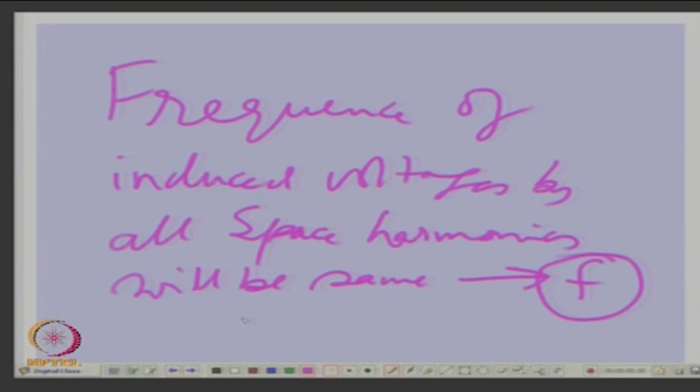But if you want to make things complicated, if the current going into the winding has time harmonics, the current is not sinusoidal. Nowadays with power electronics you make everything very messy anyway. So, current carried will also have, instead of 50 hertz, 100 hertz, 150 hertz or whatever it is. So, then what will happen? It will also induce those additional frequencies, because you will have additional fields.